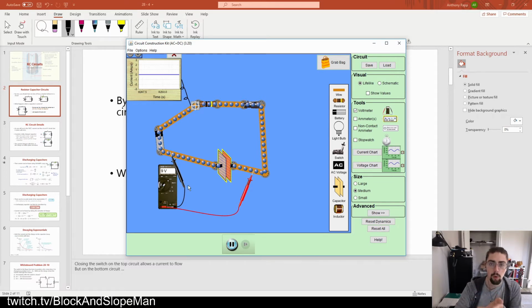Takes a much longer time to get back up to 9 volts. And why is that? Well, there's a lot more space for all of these charges to be. There's a lot more surface area for the charges to be resting on somewhere without colliding into each other nearly as much. So there's a lot more charge that needs to be moved. But now let's see what affects that rate of flow, because we just saw the time it takes, so the flow rate doesn't necessarily depend on the capacitance, at least the magnitude of it, but the time it takes to stop the current does change.